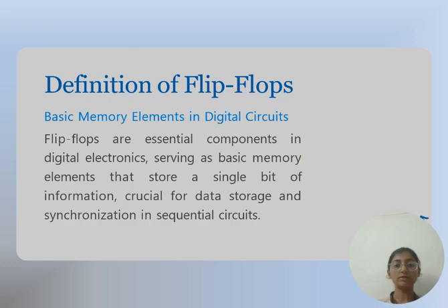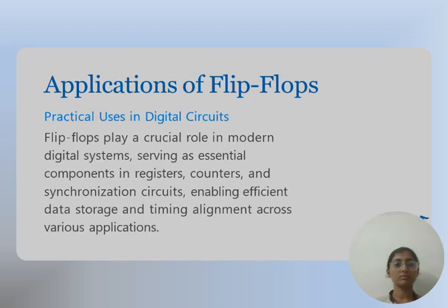Flip-flops are fundamental building blocks of memory devices and are widely used in registers, counters, and shift registers. There are several types of flip-flops, including SR, JK, D, and T flip-flops, each with specific functions and input-output behaviors. The name flip-flop comes from its ability to flip or flop between its two stable states, storing and controlling data in digital systems.